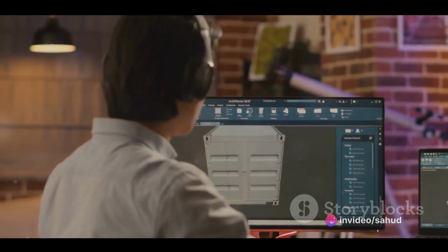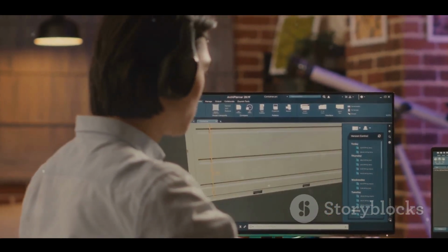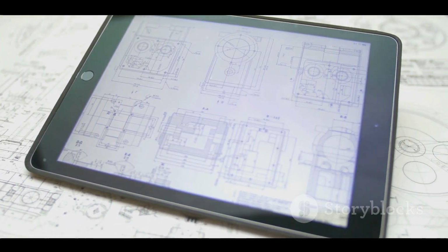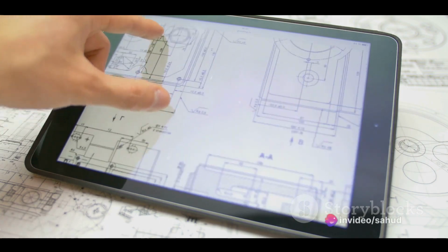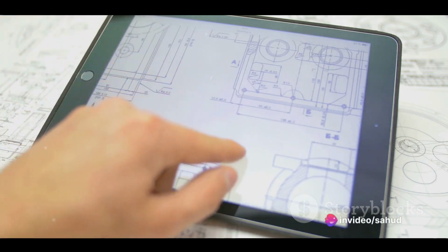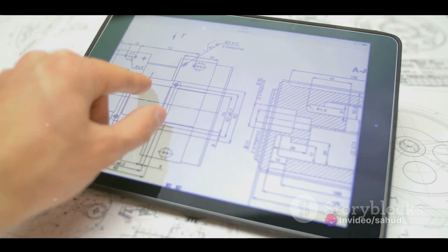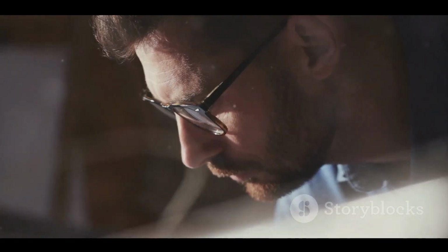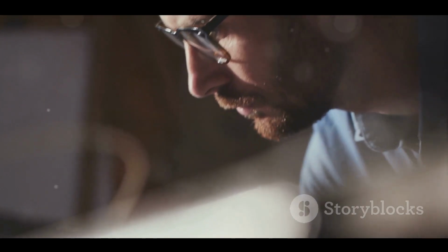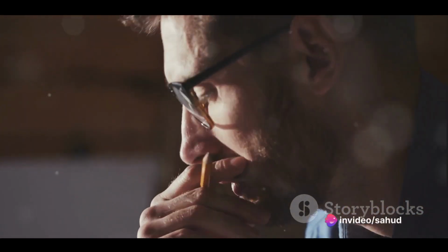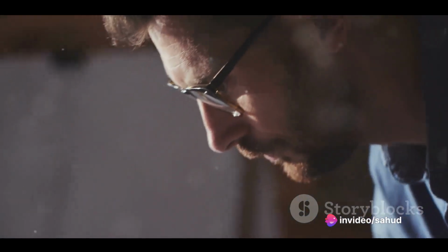Here's where the trim tool comes in handy. With a few swift strokes, you can remove those superfluous elements, leaving you with a clean, uncluttered sketch. Next on the menu, we have the Offset Entities tool. Think of this as your sketching photocopier. It enables you to create a parallel copy of a line or an entire shape at a set distance. This tool is particularly useful when you're creating multiple components with similar geometries, saving you the effort of sketching each